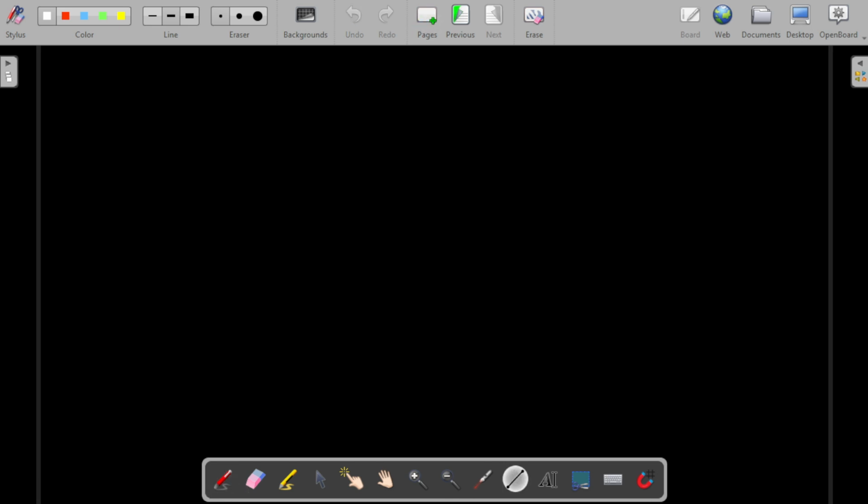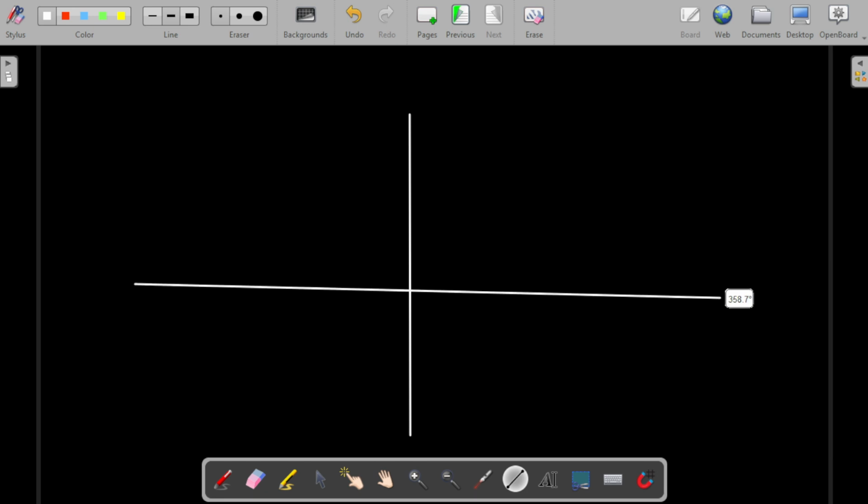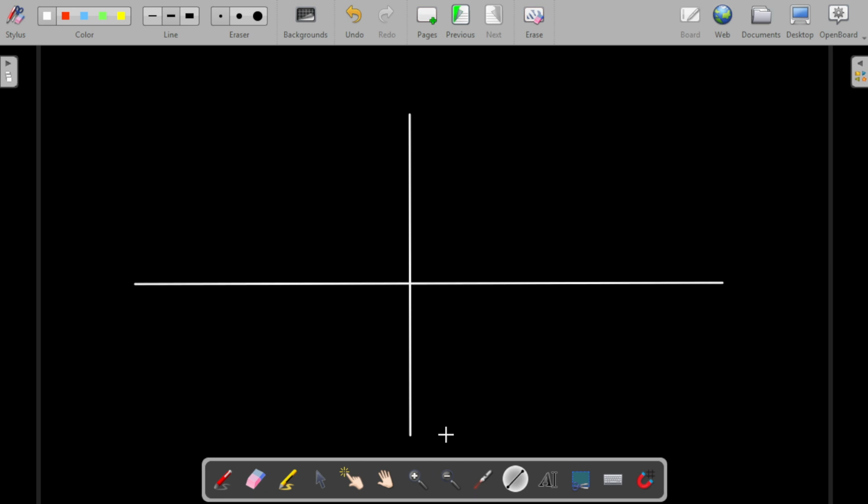So let's take the characteristic equation of the diode, the IV characteristic graph. This is one of the very important graphs that we have to look at. If we take the IV characteristic, in forward bias we know that it will be an increasing exponential current, as we know, I naught e power V by VT. But in reverse bias we know that it is a constant, so it will be maintaining a constant value, right?